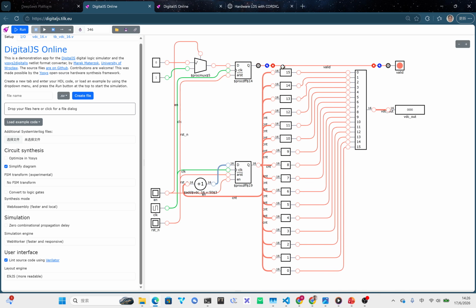That is amazing. So it just requires 17 D flip-flops? Yep. 16 of them maintain the running counter, and 1 serves as the valid flag. The entire base 2 module takes up a grand total of 72 logic cells. I mean, it's functionally microscopic.